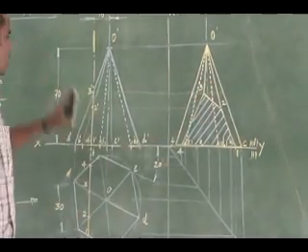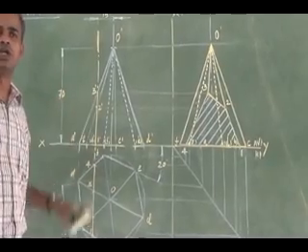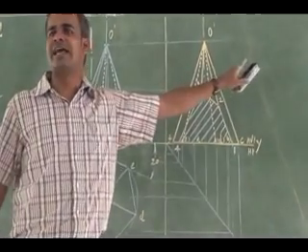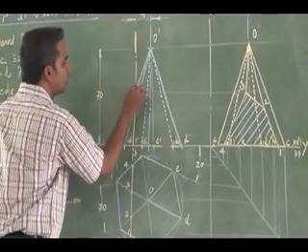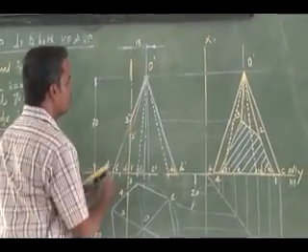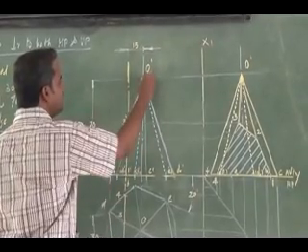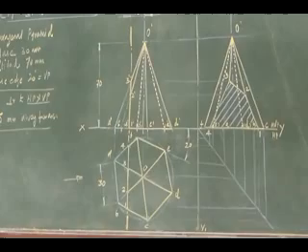So what is asked? You are asked to draw the front view, top view and sectional side view, which is the retained portion of my front view. So that alone you have to darken again. Finally you have to darken the retained portion of the front view.